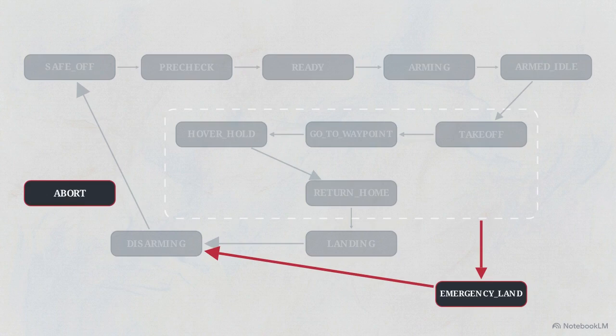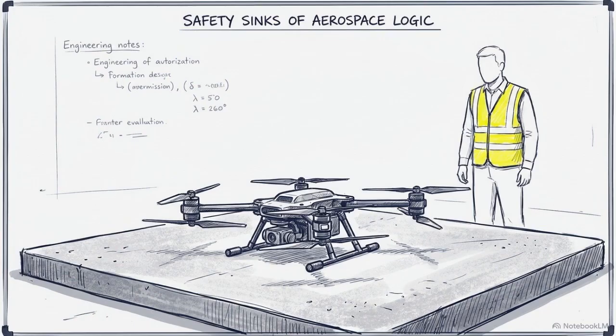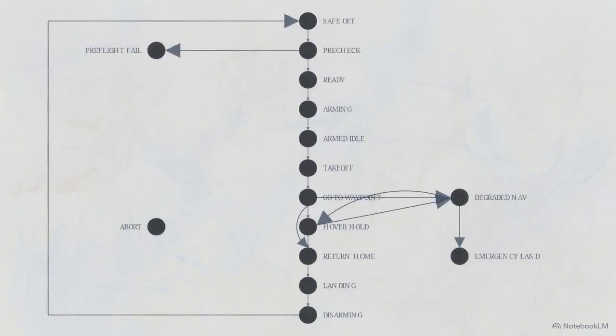Scenario S2 involves a manual abort command from a human operator. This similarly interrupts any autonomous state, routing the logic into a distinct abort state and handing authority back to the operator. Manual overrides and critical hardware faults strip control away from the mission logic. These pathways are designed to be one-way transitions to ensure safety. These hard-coded sync nodes act as the structural floor for the drone, ensuring it always has a predefined recovery pathway, regardless of the fault. The complete Phase 0 state diagram maps all potential inputs to predefined outcomes.